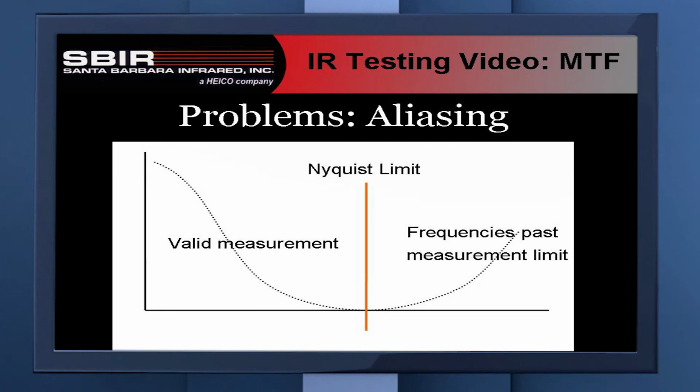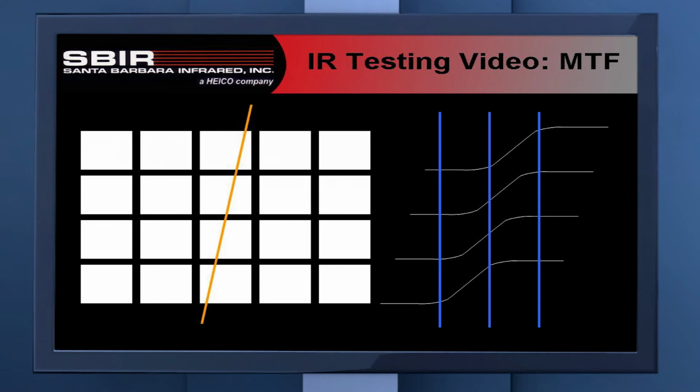And what occurs is, as shown in this slide, you have a signal that's a much higher frequency than what you're sampling at. And so you take it at the wrong spot and produce what you think is a lower frequency result. You're taking measurements of a high frequency signal, but it appears to be a low frequency signal. That's the aliasing problem that we run into.